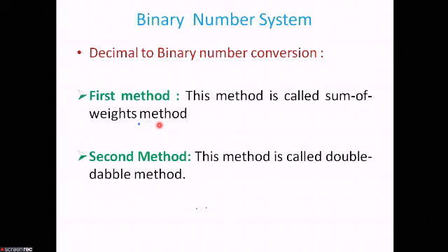In the successive multiplication by 2 method, the given decimal fraction and the subsequent decimal fractions are successively multiplied by 2 till the fraction part of the product is 0, or till the desired accuracy is obtained. The first integer obtained is the MSB. Thus, the integers read from top to bottom give the equivalent binary fraction. To convert a mixed number to binary, convert the integer and the fraction separately to binary and then combine them.